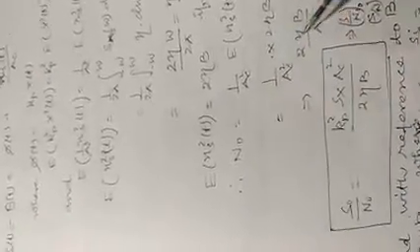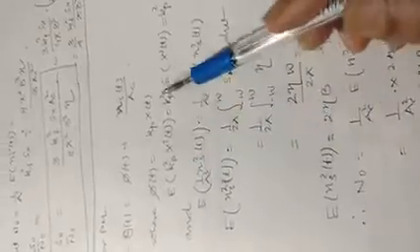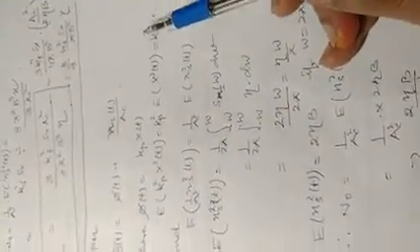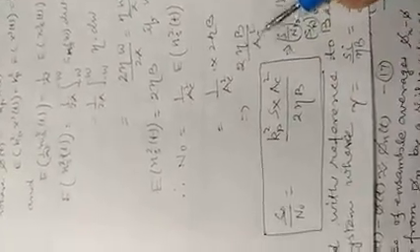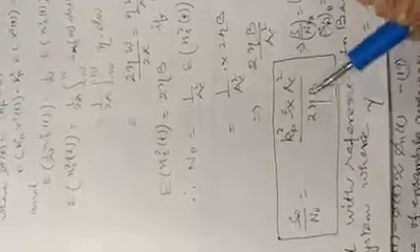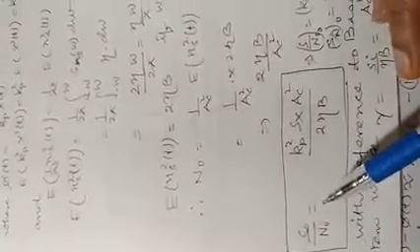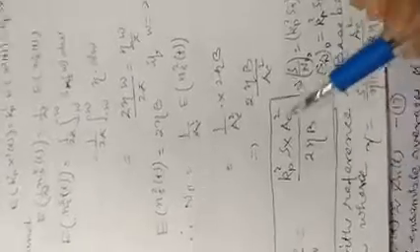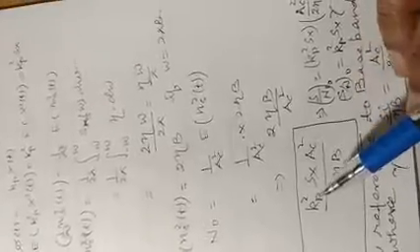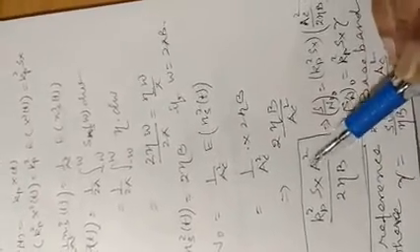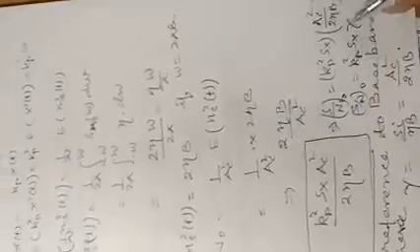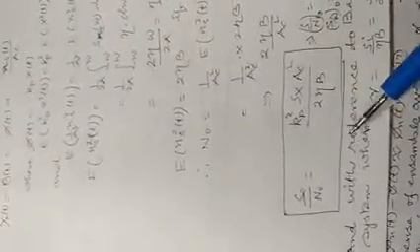So we can take the signal to noise ratio again from this formula, kp square Sx divided by 2 eta B Ac square. This becomes the signal to noise ratio at the output of the phase modulation system's receiver side. So here again we want to write in terms of the baseband system, then we can write kp square Sx, we can separate, and Ac square by 2 eta B is the gamma. So we can replace it and we can get this signal to noise ratio for the PM systems.